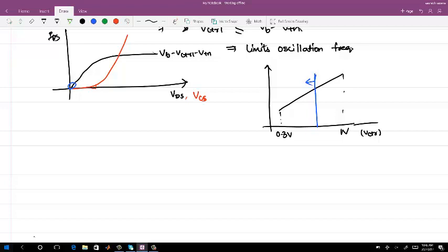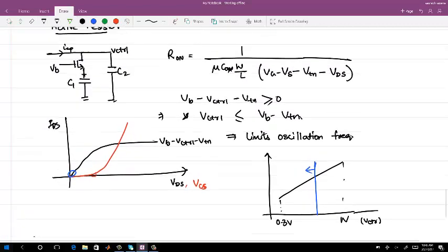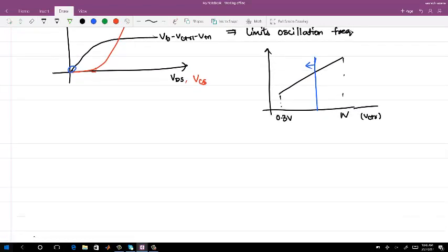If you use active resistance, you have that tunable property, that you can easily tune it, but it comes with the drawback that you will have more leakage and you may have a limited control range, whereas using a passive resistor doesn't give you any such problem. The only problem is the controllability. Okay, so that is the passive resistor, which you realize.